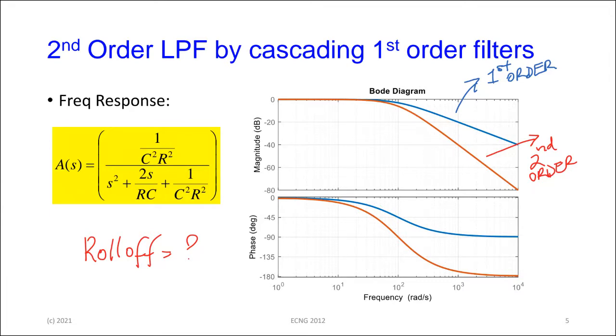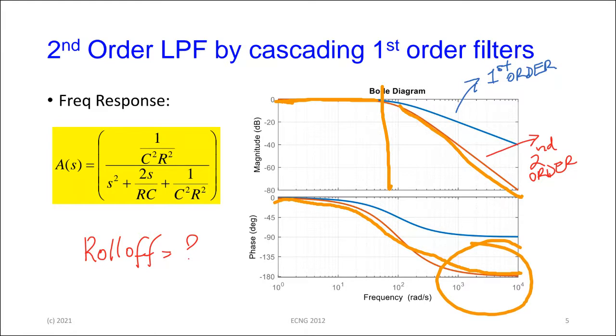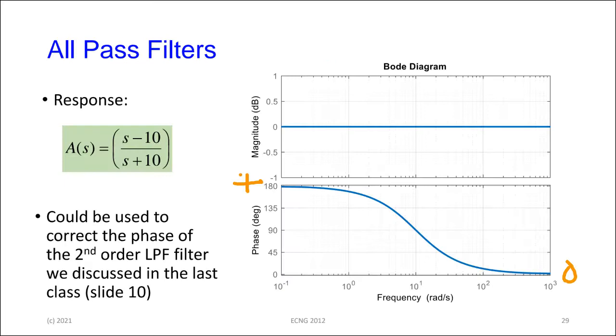The frequency response is going from 0 to minus 180. So it's stopping a band. We have a nice flat pass band here. It's rejecting something that we don't want, but at the same time, there's a phase response that is changing from 0 to minus 180. We just saw that I could create a filter that does the reverse, that goes from plus 180 to 0.